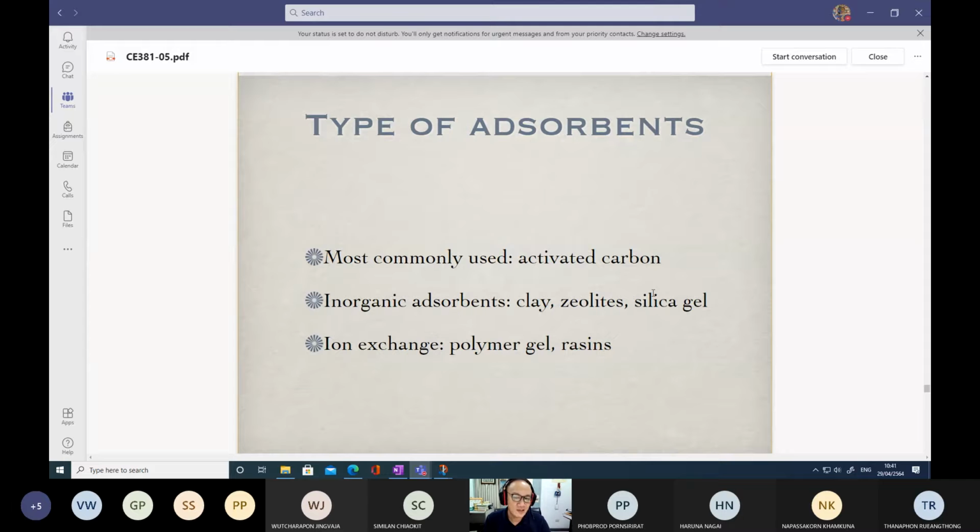Activated carbon is good enough to remove compounds associated with taste and odor generation, and it can also remove some trace pollutants like the remaining organic compounds. In some countries, they require the COD in the wastewater to be even less than 60 milligrams per liter.